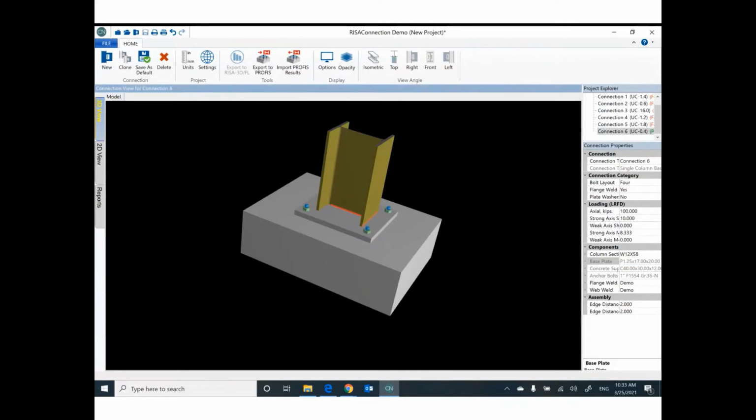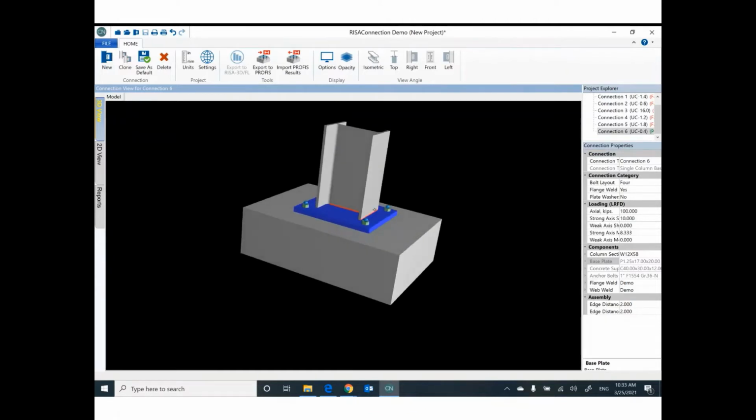In this case, it will be called base plate. Bolt it by or fix it by these washers and nuts. Then get your column and weld it to the plate. This is the connection between the column and footing.